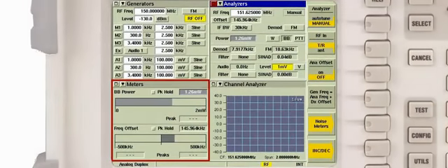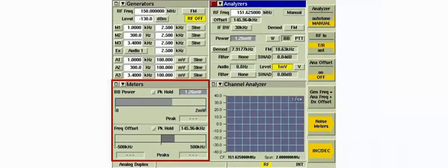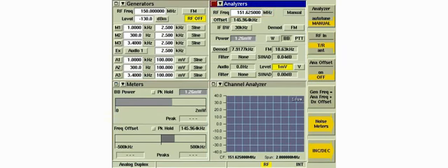In this test setup, the broadband power meter and frequency offset meter are selected for display on the meter's tile. The radio transmitter is connected to the TR connector, and the analyzer's RF frequency is tuned to the radio's transmit frequency. We're ready to key the radio.